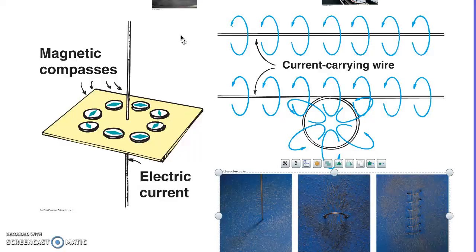Okay, but they use the magnets by turning them on and off to make them go faster and faster and faster around here, and that's the same kind of thing, and it's some type of electromagnet. Now, the problem with these electromagnets is that you have electricity. The more and more electricity you put through, the more and more coils you have here, you have more resistance. And if you have more resistance, then you have more heat. Okay? And so that's what limits how strong.